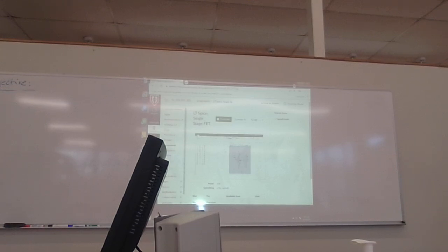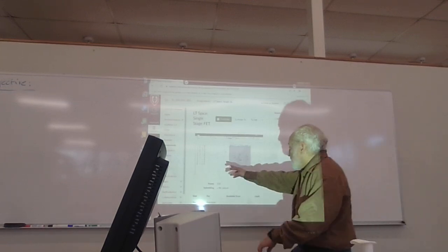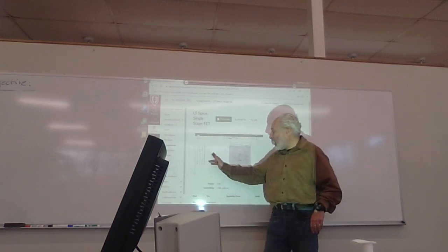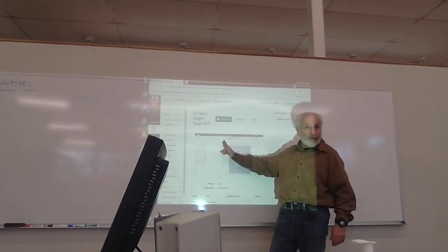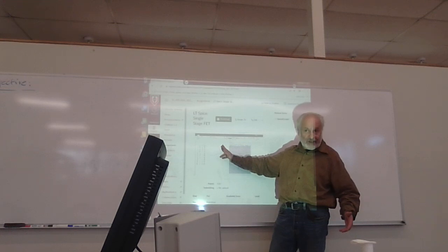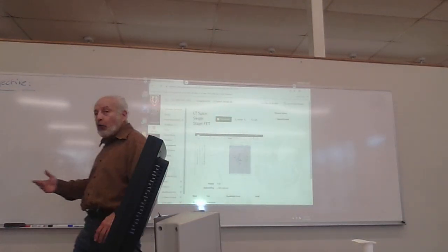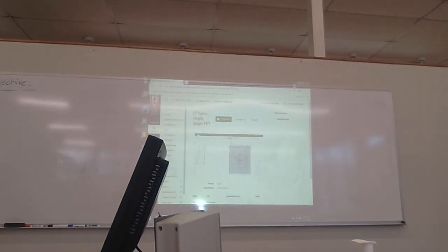Does that make sense? And we get to see the pinch-off voltage is in the voltage right here, this VGS versus ID. And the highest level of current is IDSS. Does that make sense? Okay. And again, I'll go through this analysis. That's when I turn off the light and do a sim. That's what we're going to do after what I'm going to do now.